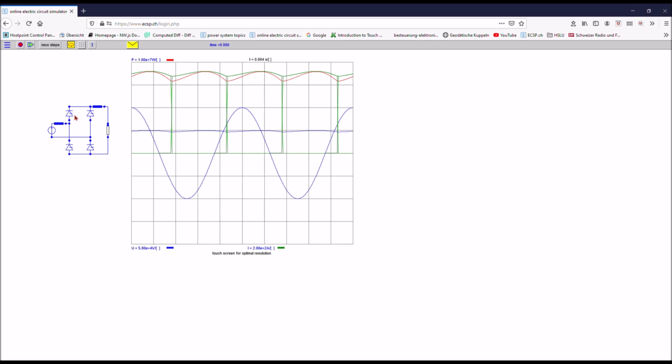So now I can look at what happens at the thyristors, and you also see the commutation between the pairs of thyristors. I can increase or decrease this commutation time. You can see here, I can further smoothen the current by increasing the reactor at the load side.